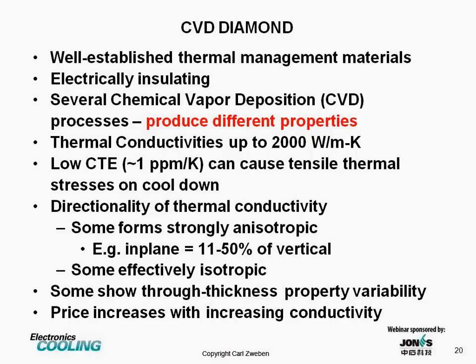And this is unique in that it is electrically insulating. That is, of course, a property of diamond. We have thermal conductivities up to 2,000 watts per meter Kelvin and low coefficients of thermal expansion. Unfortunately, it's actually too low. The goal is a range of 2 to 7.